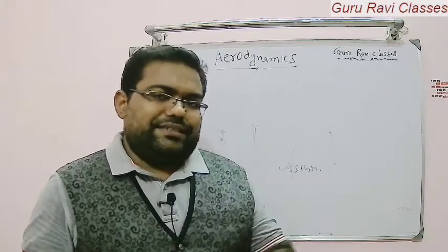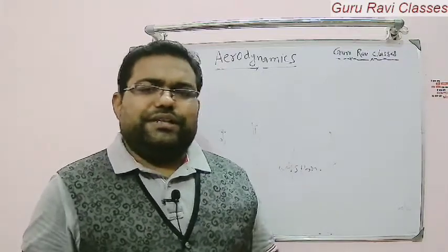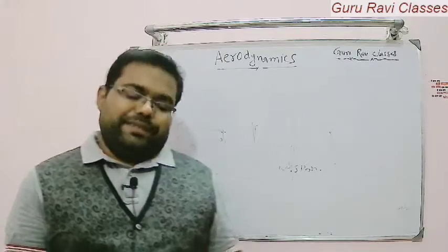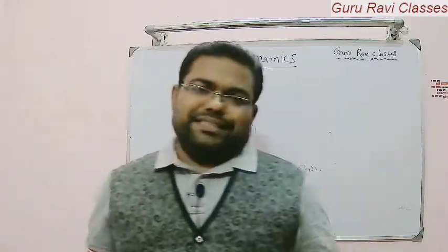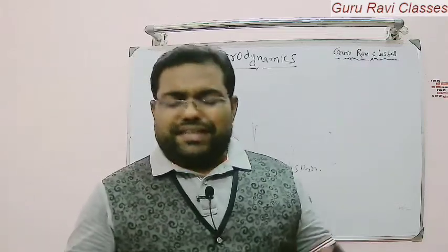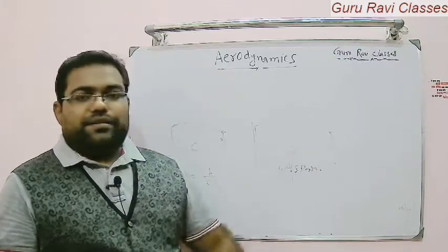So there it is 6 to 8, and for sports aircraft we can go up to 16, right? But usually it's not recommended. It may be somewhere around 10 to 12. And passenger aircraft will be somewhere in the intermediate range, between 6 to 12, something that can be used in passenger aircraft or transport aircraft. Aspect ratio will be something like this. Aspect ratio and wingspan, that is clear.